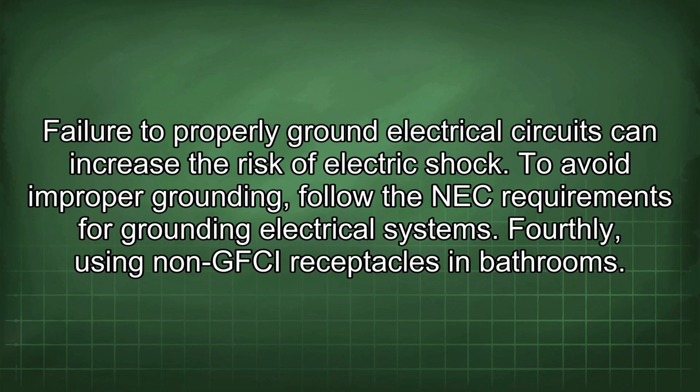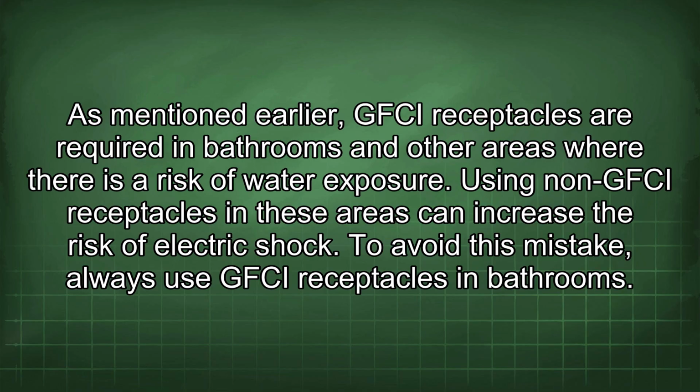Fourthly, using non-GFCI receptacles in bathrooms. As mentioned earlier, GFCI receptacles are required in bathrooms and other areas where there is a risk of water exposure. Using non-GFCI receptacles in these areas can increase the risk of electric shock. To avoid this mistake, always use GFCI receptacles in bathrooms.